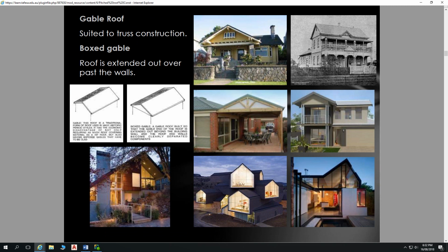Following on from that, also fairly conventional form of roofing is a gable end. So those gable ends are formed in all sorts of ways. We spoke a little bit about timber portal frames just before the lesson there. These type of systems will be typical. They may be manufactured from engineered timber, but typically that will be manufactured from hot rolled steel sections to be able to keep the profile, the thickness of that wall very thin to give that a far more elegant look.